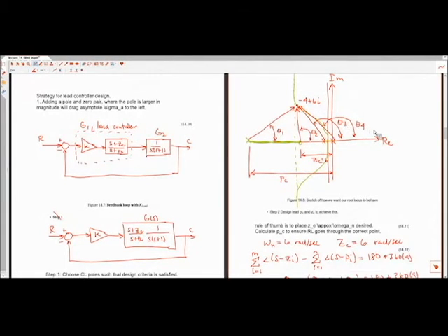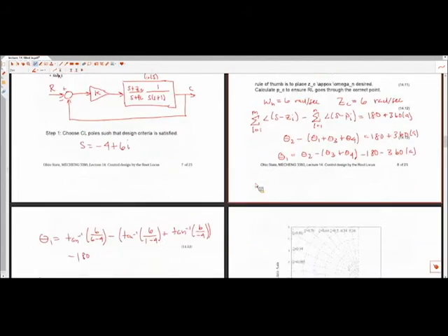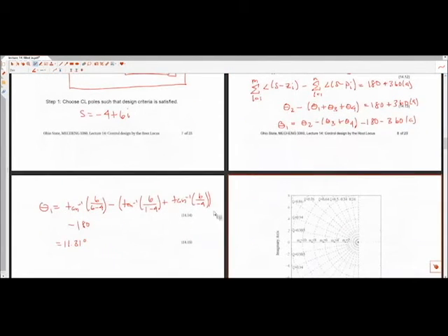Right? So if you were to just put in what I have here with the typical ATAN function in MATLAB, this is going to give you the wrong answer. So you need to use the ATAN2 function. If you have not used that function before, I would take a look at the help files to understand how to use it, but that's going to be necessary to get these ones correct.